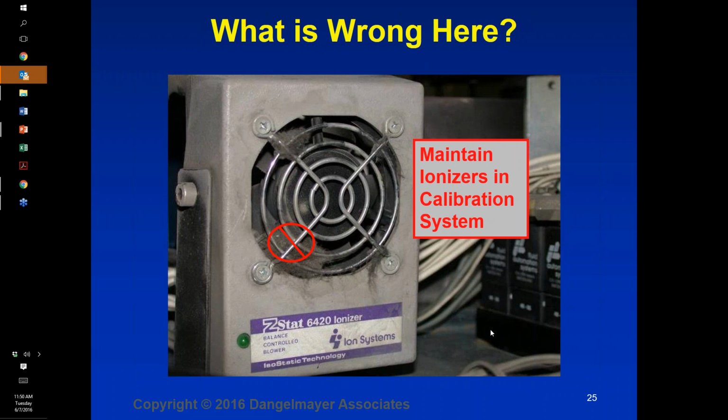AC ionizers will produce more ozone than DC ionizers, that is true, but again, they're well below the levels that are specified for human work environments. What I would not do is walk into the burn-in room where somebody is burning in 200 or 300 ionizers in a very small area. You'll find very significant levels of ozone in that situation, but not in any common use of an ionizer in a work environment.